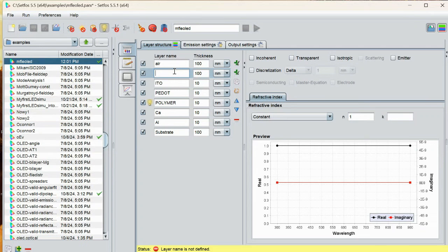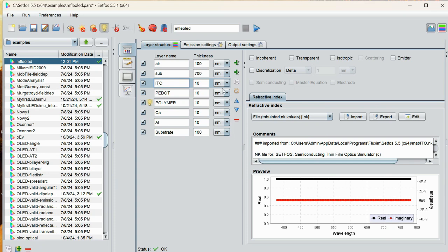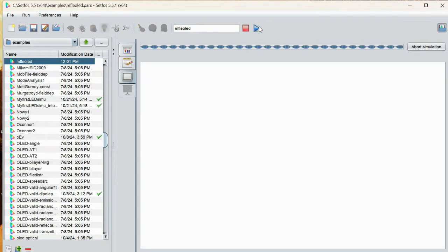Next we will give the name substrate layer. The layer structure will change with the thickness. For the thickness above 500 nm you will consider discretization elements at 100, because it reduces the amount of data, which can improve performance for whole extraction. Now you will run the simulation.